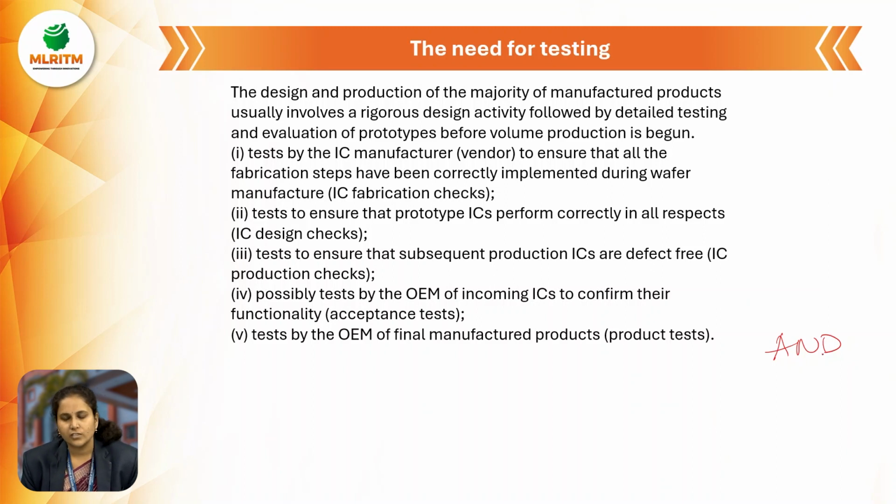For designing an AND gate, we need a two-input AND gate. We get four combinations: 0 0, 0 1, 1 0, and 1 1. The outputs for these combinations are 0, 0, 0, and 1. So this is the proper output of the AND gate.